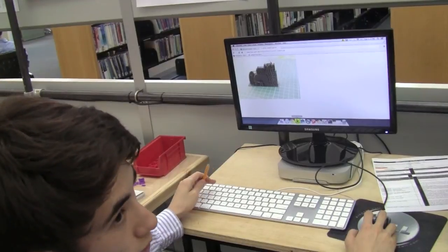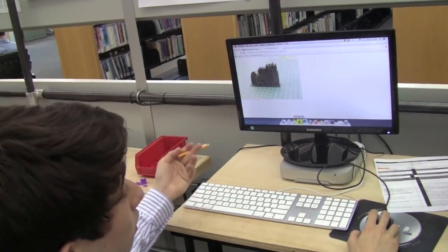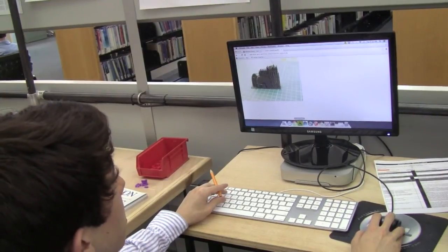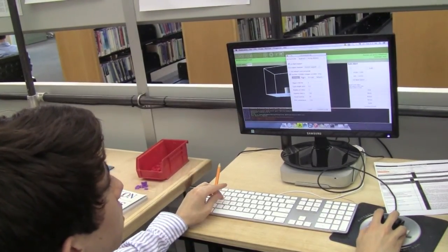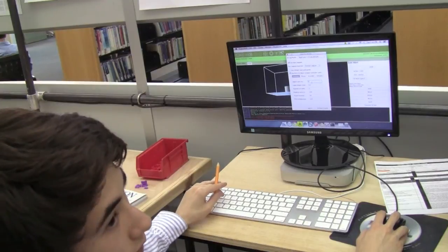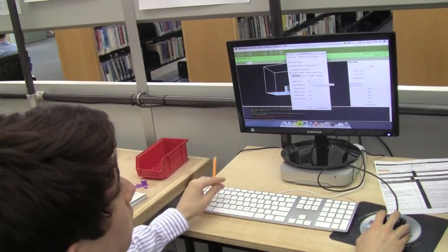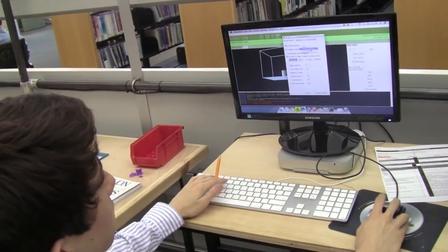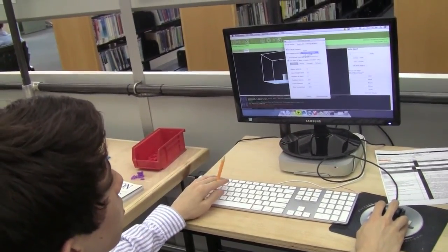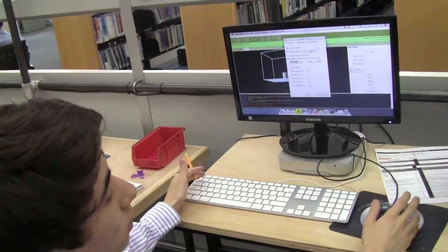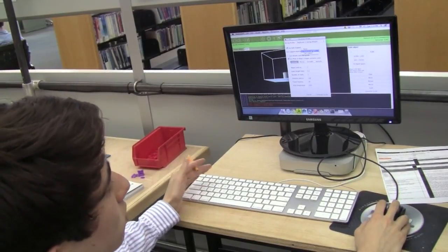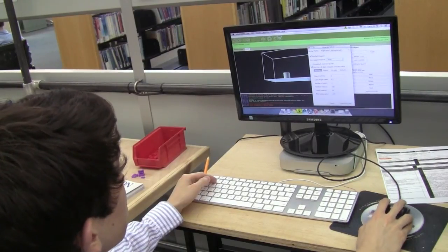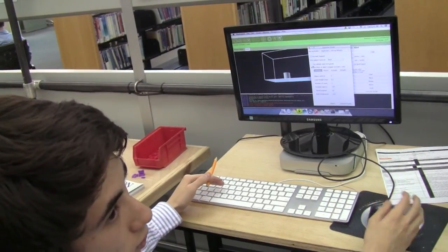Usually model makers will understand that if they're putting it on Thingiverse for 3D printing, so usually they'll try to eliminate any overhangs like that. And I'll also explain object infill, which is kind of like a pseudo infill, but that's for solid models, so it's kind of different. But anyways, normally you would use exterior support unless you really need full support. And for this model, you wouldn't need any support or a raft because there's no overhangs really.